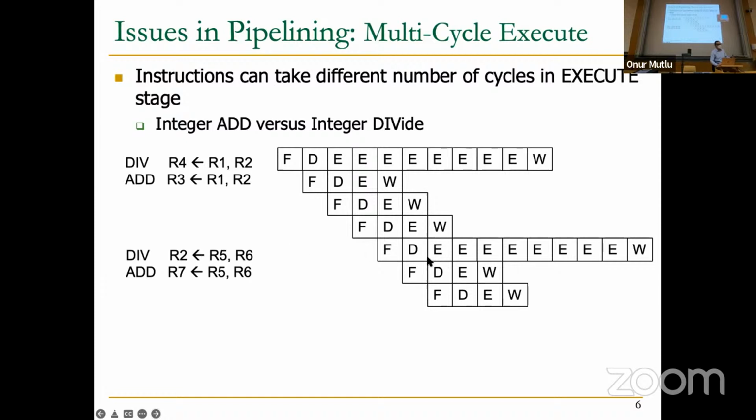The next instruction is a divide. Again, the pipeline is being filled sequentially, but instructions are writing their results out of order, right? So by the time this division instruction writes its result, 5 later instructions have already updated the register file with their results. It could be memory also, but let's keep things simple right now.